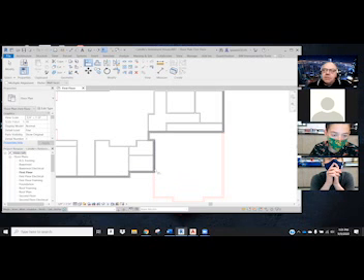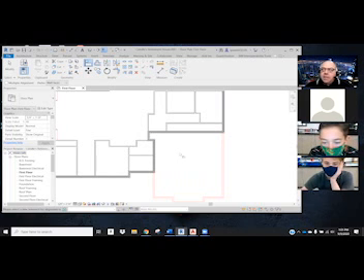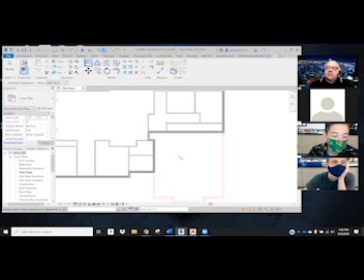The walls that are between the garage and the house are called separation walls. They're very special walls in that we have to put different gypsum board on them than anywhere else in the house. We have to treat them like a commercial wall and use 5/8 gyp board on them. That would include if you have a room over the garage, the ceiling of the garage also has to have 5/8 gypsum board. Just in the event that we have a fire in the garage and there's a bedroom over it, which is typically the case, we don't want anybody to lose their life if they don't have to, okay? We want to save people if we can. So we need to create what's called a separation wall.